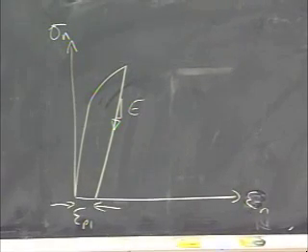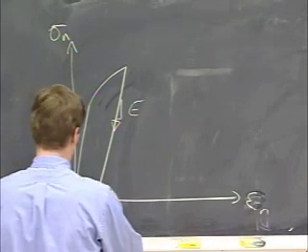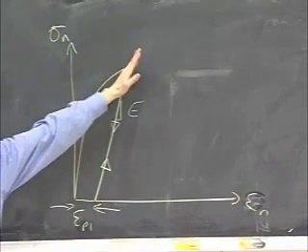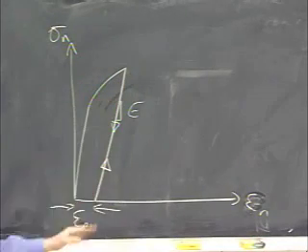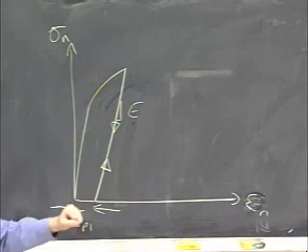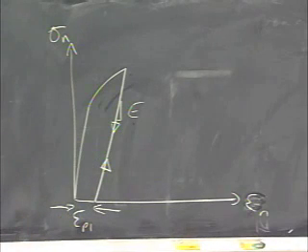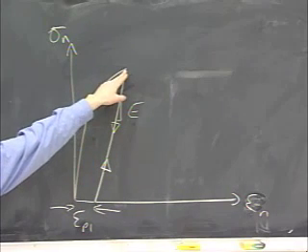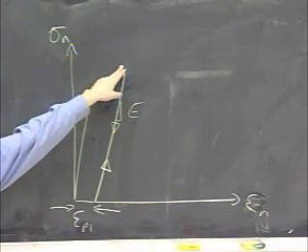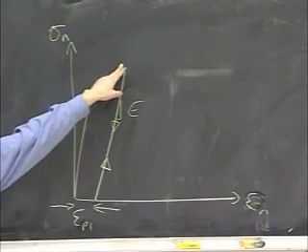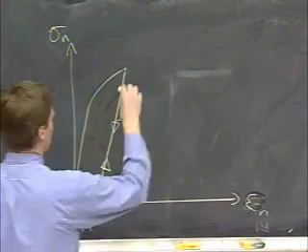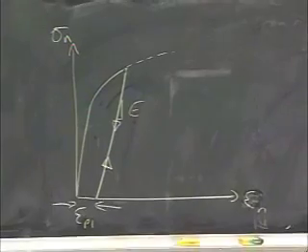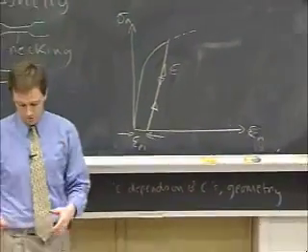And then if we reloaded this, we would reload again with the same modulus of that material. The modulus doesn't change because of this plastic deformation until we hit this new yield stress. The material has apparently got stronger because we've done this deformation to it, and would continue on until we get tensile failure. Yes, Ben?